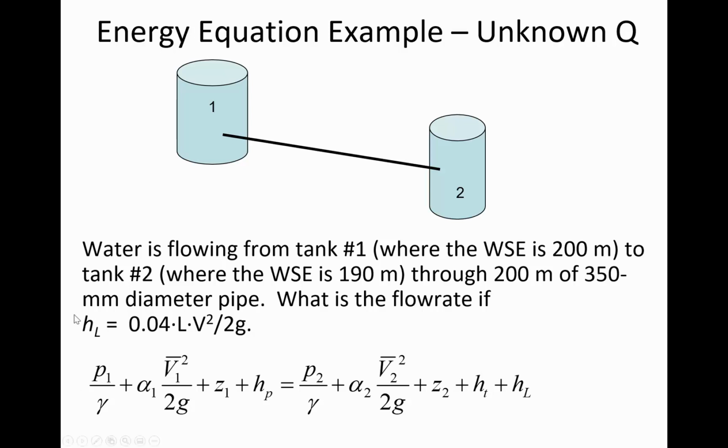So what I've given you here is an empirical simplified expression that is addressing how much head loss you can expect for this particular pipe. And so what we're saying is this is a formula that calculates the head loss as a function of pipe length and the flow velocity.